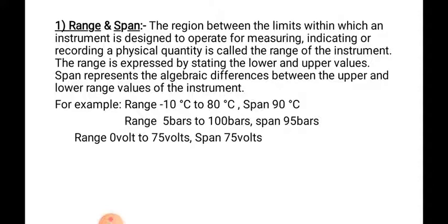I think all of you understood what range is. The next parameter is span. The span represents the algebraic difference between the upper range and lower range values of the instrument.